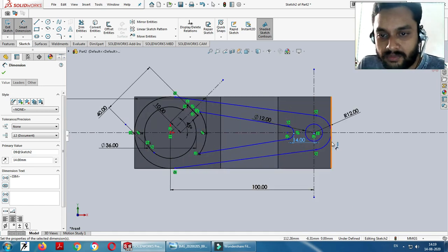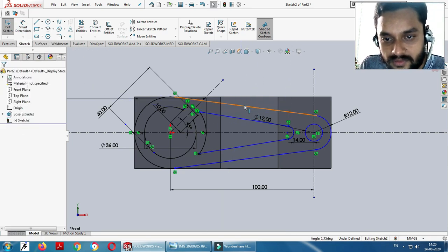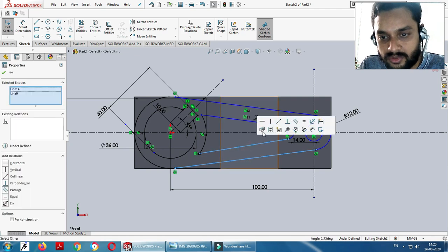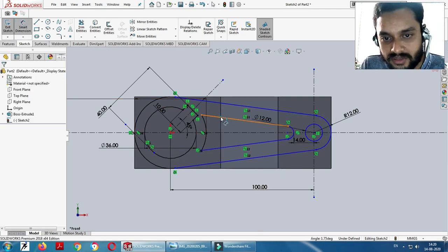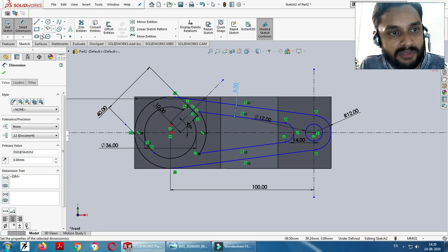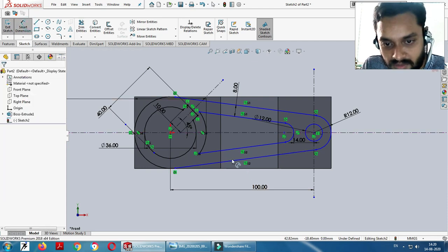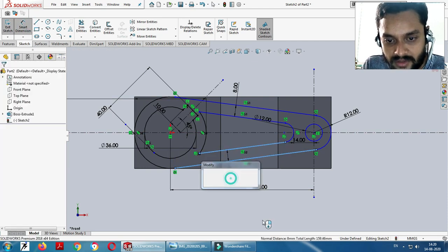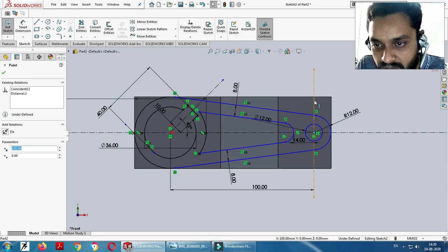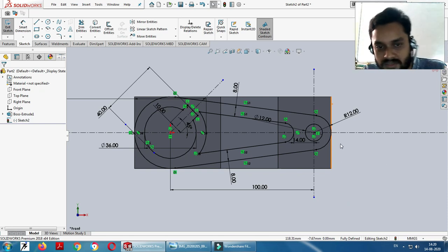Still it is in blue color because, let's say, first of all, these two should be parallel, correct. Again these two should be parallel, and the dimensions should be 8 mm. While trimming, we have removed some of, I think, the constraints. So you need to again give this 8, and then, correct. You can specify the other constraints like this, correct. So this is the final sketch.